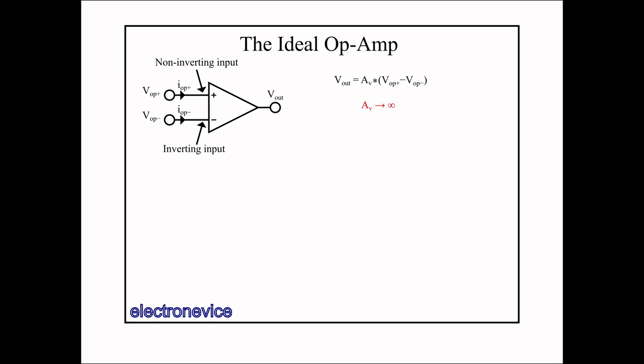As we'll see, however, this ultra-high gain, along with negative feedback, allows the user to control the op-amp circuit's net gain with some simple external components, so that with the same chip, one can generate a wide variety of gains and circuit properties depending upon the application's requirements. In the ideal op-amp, the gain approaches infinity.